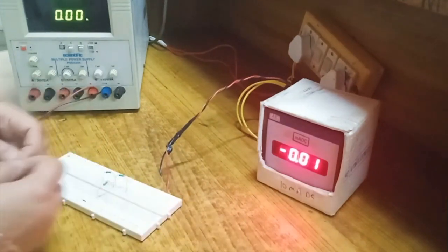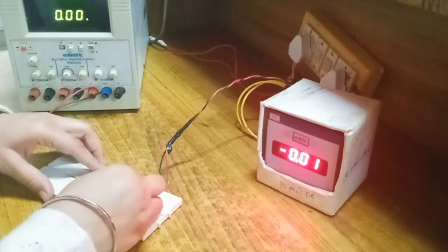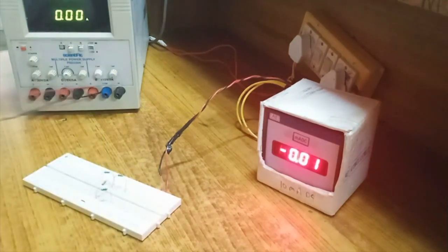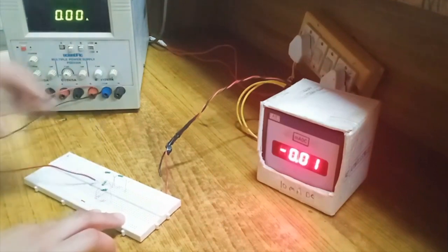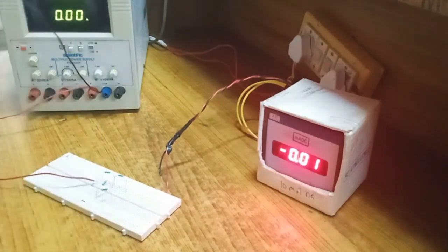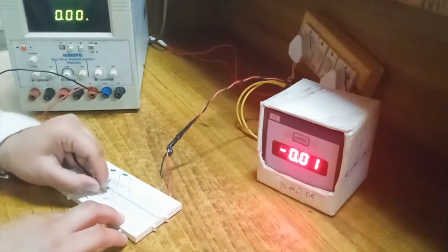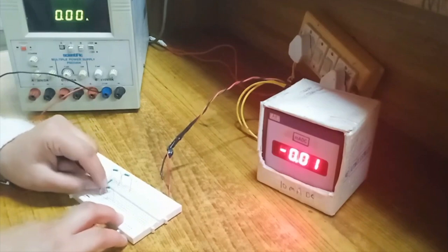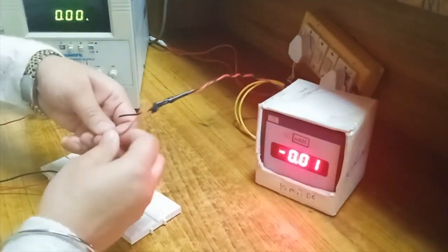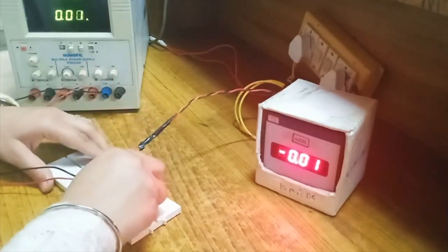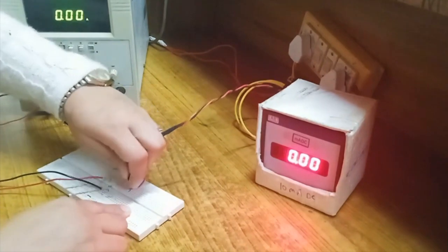RL 1 kilo ohm, the input supply: positive with the first terminal of 220 ohm resistance and the negative where RL and 220 ohm resistors are connected together. So again we have a column wise connection. And finally ammeter, the positive of ammeter with 220 ohm resistance like this and the negative with RL.